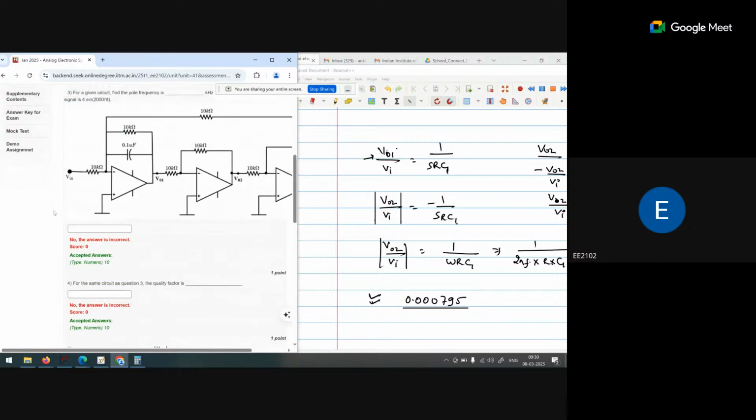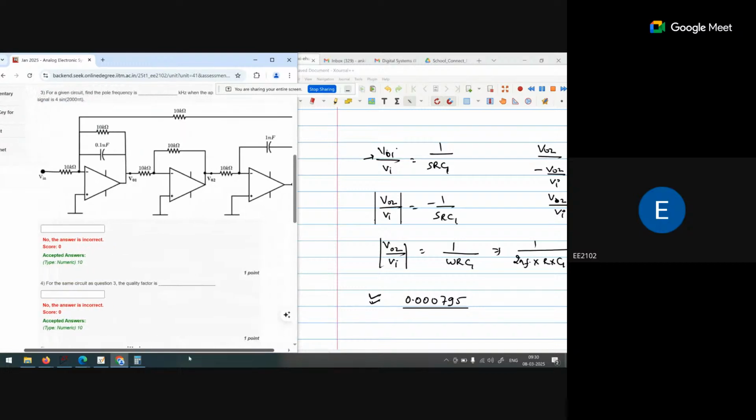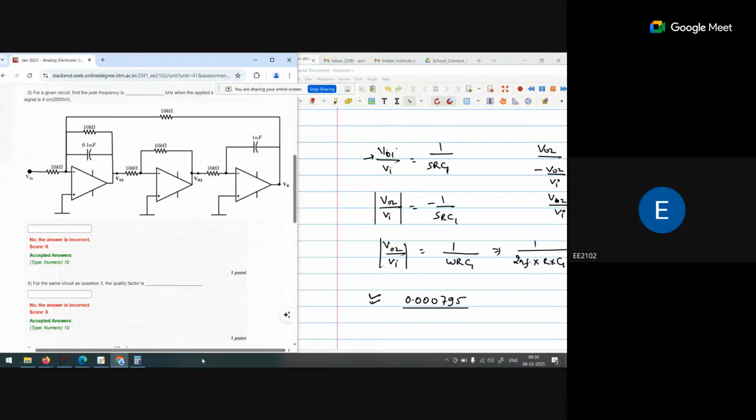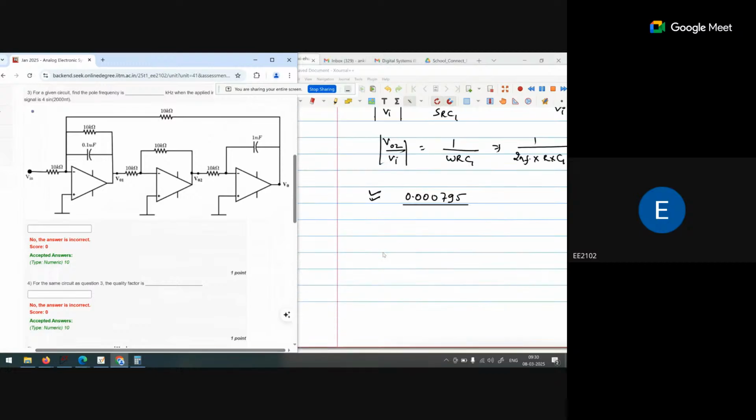Now if you see, there are three operational amplifiers used. First of all, looking at the last one, if my V out 2 is the input and V out is the output, then that particular third one will behave as an integrator. So third one is basically the integrator.